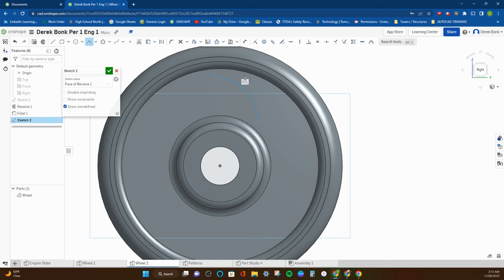And by pulling this, I can flex the direction of this curve however I want. So I'm just pulling this in a random way and hitting enter when I see that line come up. All I'm saying is I'm going to make kind of like just a flared out cut like this. It almost looks like an eye. And hit enter. And pattern that now.